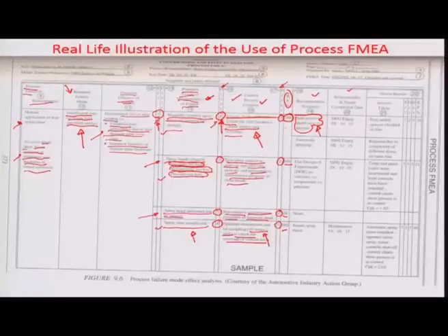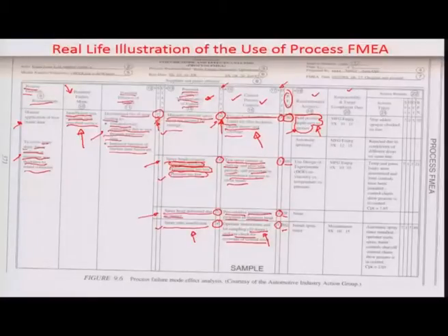In this particular case, adding a positive depth stop means that if the manually inserted spray head is not inserted to a certain level, the line will not work and will stop. So it has to ensure that the lever gets hit and deflected for a count, so that the PLC can signal the line to start again. This foolproofing has now led to a situation where the occurrences of this particular event have been reduced to almost 20% of the times.